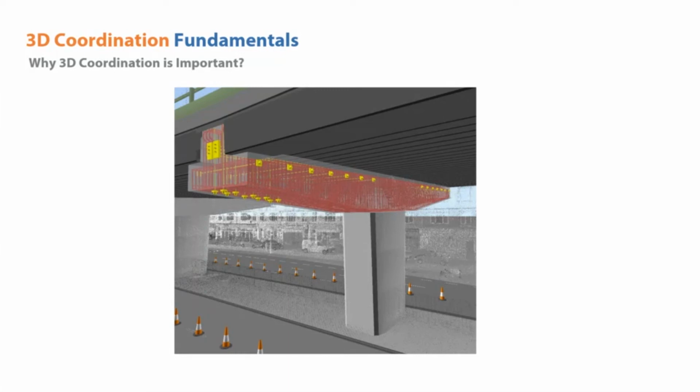3D coordination on BIM software offers both predefined and customizable modeling environments and uses standardized building components that facilitate the development, transmission, and connection of building systems in 3D. So this provides the conflict detection mechanism to all project stakeholders that aids in the identification of physical interferences between components and is an advance over the traditional 2D coordination process. So this allows stakeholders to engage in coordination processes earlier in the project lifecycle. Identifying and resolving coordination issues during the design process in a virtual environment is highly valuable to all the project stakeholders when working with the 3D models.